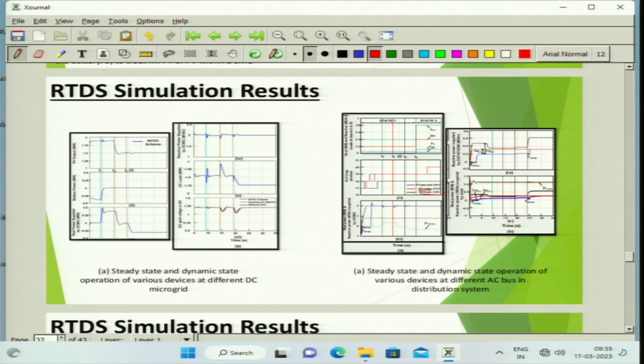So, we have compared them: the blue color one is proposed, red is existing, black is without. You see here the advantage in the blue color one: there is a delay time, and we are not injecting any reactive power, whereas in the existing CVC scheme there is a hard limit of 40%. It senses a dynamic state, reaches 40%, and is hard limited, whereas the without scheme, black one, keeps on injecting reactive power. So, there is no boundary for it.